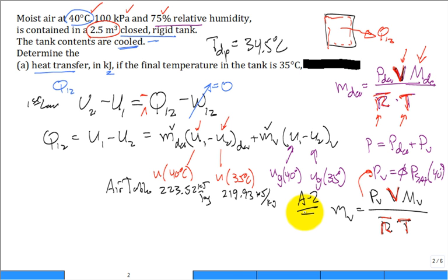Table A23 is on a kilomole basis. So I'd have to get the number of moles. Well, how many moles of vapor are there? It's the mass of the vapor divided by the molar mass, 18.02. Yeah, and there you go.